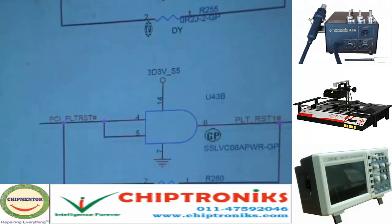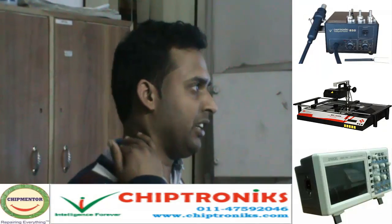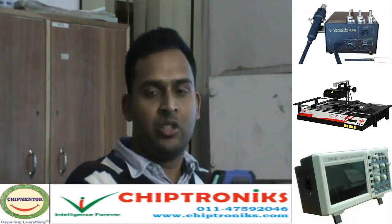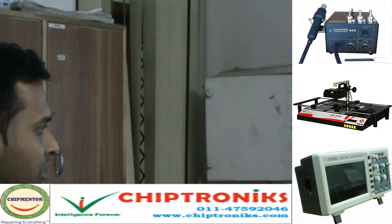See, 3.3 volt at pin number 22 of the mini connector signifies 2 things. I will discuss this when I go into the clock generator. If 3.3 volt is present at pin number 22, then 2 things are okay: one, your ICH, and another, the clock generator. We will see how these 2 things are related. We can see over here also.